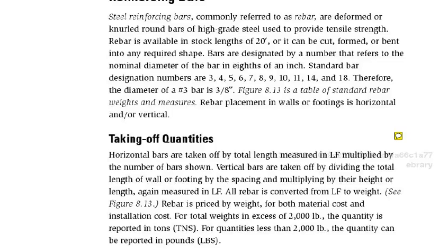Reinforcing bars are, I'd say, the primary type of reinforcing that you'll see, and you'll see it specified in the plans in a couple places, so make sure and look at the plans, all the sheets to find it. Rebar comes as designated numbers, and generally there's a 1/8 inch nominal diameter increase, so you'll see a 3, 4, 5, 6, 7, 8, and every number 3 bar is 3/8 of an inch. A 4 bar is 4/8 of an inch.